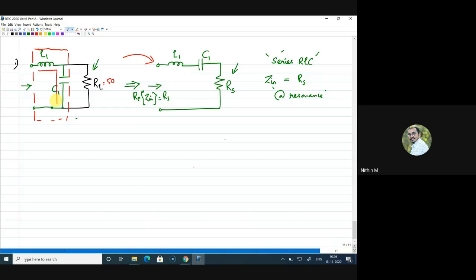But most of the time, it all depends on the value we are arriving at, the inductance value or capacitance value. Now see, whenever you draw a single line on a substrate, a single metal line as a layout, that itself will give you some inductance value. Sometimes even small bond wires also act as inductance. So for transformation, we definitely use these kinds of techniques.